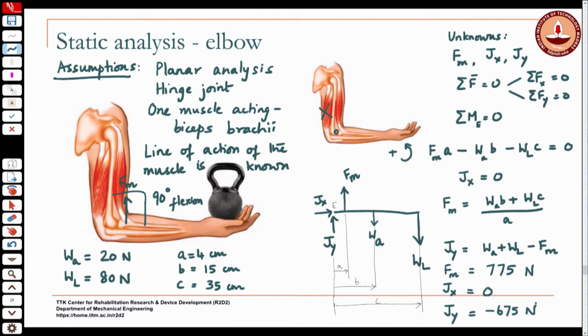Okay. So, if you see here, the muscle force that is developed is almost 10 times the load that is being carried. And that is because of the small moment arm at which the muscle acts.